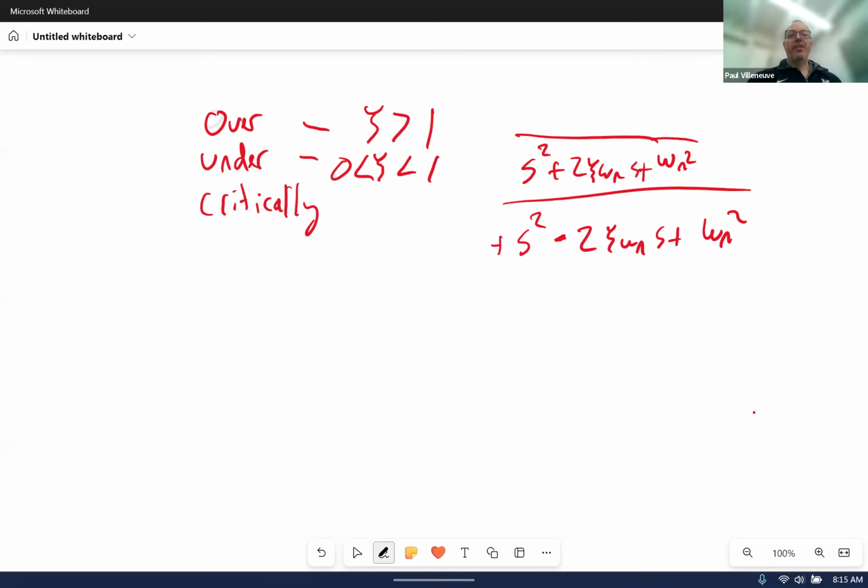All these coefficients have to have the same sign, right? Do they have the same sign? They do not. So any negative coefficient, when the rest are positive, is going to be an unstable system. So how can you have damping if the system blows to infinity? It's inversely damped, right? So you can't have a zeta less than 0 because you wouldn't have any damping at all. The system would actually be growing larger.